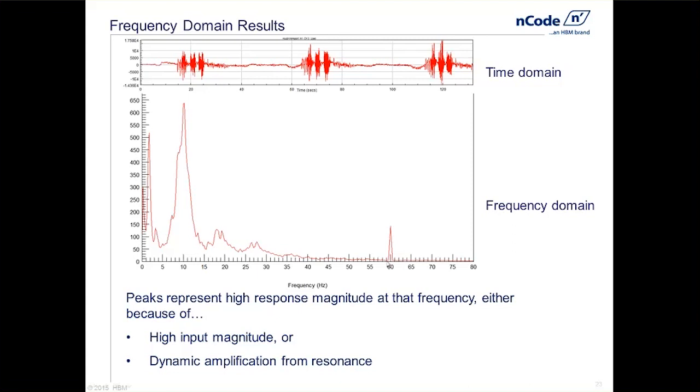This one being quite narrow and much larger in magnitude than the surrounding frequencies of, let's say, 57 Hertz all the way up to 62 Hertz, might suggest that this was measured time series data collected maybe in North America, perhaps in an indoor lab where we have a lot of interference from the AC electricity. Perhaps it's picking up some of the noise coming from the fluorescent lights in the lab, which we would definitely be able to hear if we were actually present in that room.